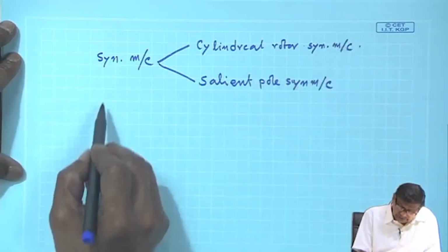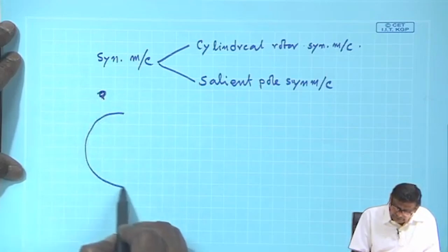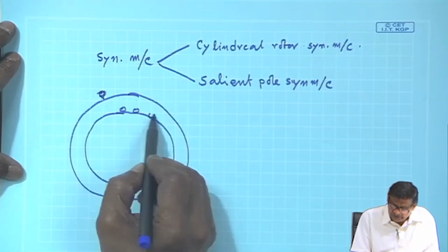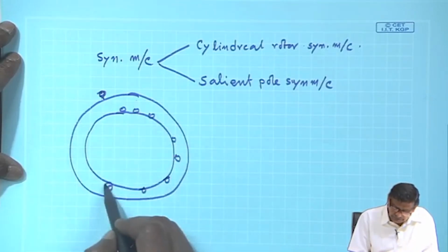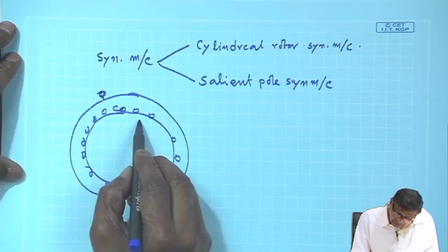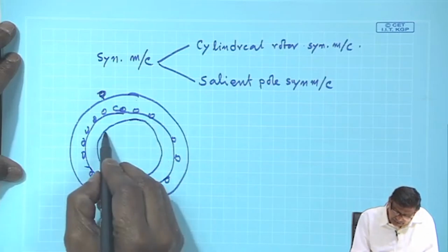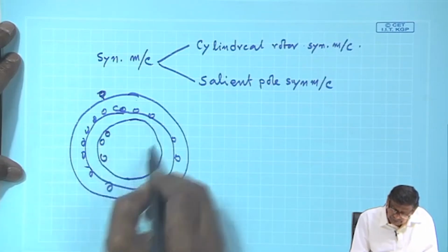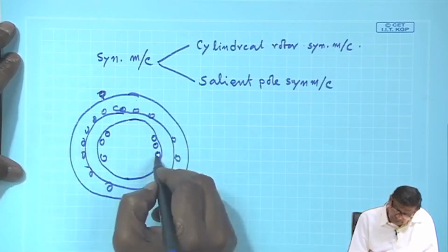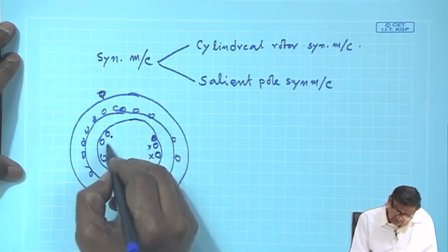Structurally, it is like this. In case of a cylindrical synchronous machine, this is the stator, which has 3-phase distributed winding on the stator inner periphery in the slots we have discussed, and the rotor is also cylindrical in structure, and there will be simple winding coils, where I will pass DC current, say cross this side and dot this side.